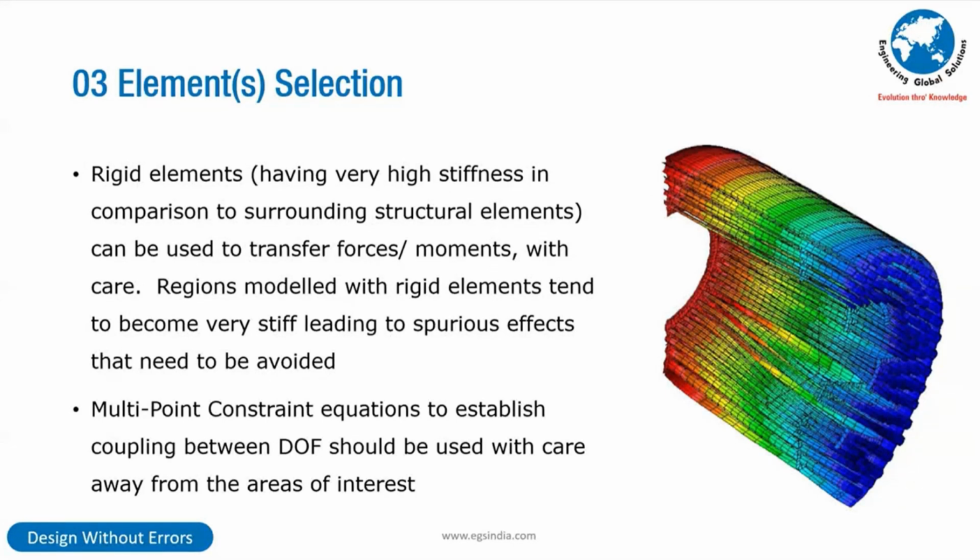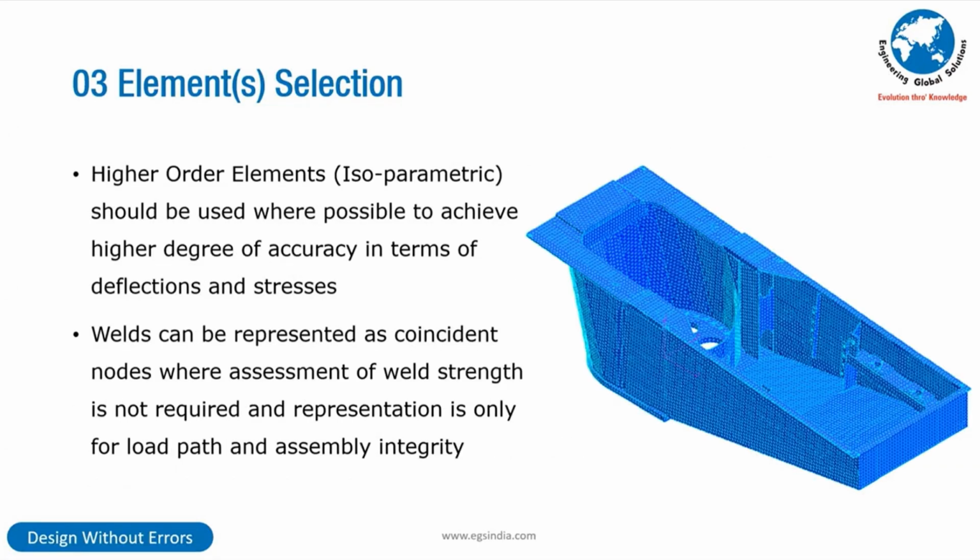So the multi-point constraint equations, people need to understand this, especially in advanced finite elements. What you're seeing there on the right side is a nacelle frame used in the windmill. The stiffness of the windmill structure is extremely important. This houses the generator, the gearbox, the reduction elements, everything comes inside this. So the entire unit is going, the entire load bearing structure is coming, the reaction torque is coming in here. Would I use anything other than an isoparametric element? The stiffness is very important here.